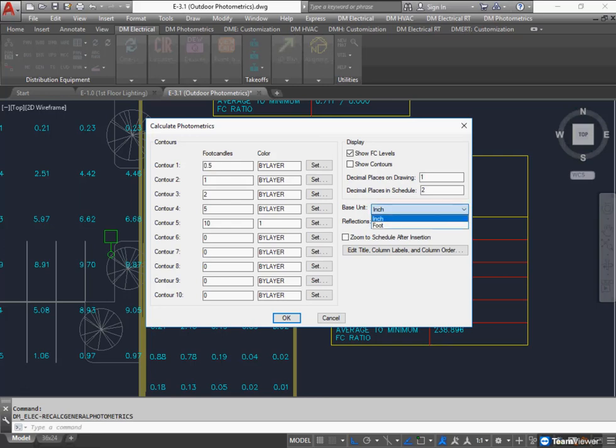We have the option for the base unit for your plan. Typically, this is going to be inches because most of our customers are working with inches. If you have some civil plans use the base unit as a foot, and so if it is, then you need to adjust this so that all the calculations and distances are right. So you just need to know if you are working with a drawing that has a base unit of an inch or a foot. If you do a calculation and it looks terribly off, you can just change it and see what happens. If it's taking a long time, you can also change this, and often switching from inches will speed it up because you have the wrong unit chosen. So it's important to get the right unit selected there.